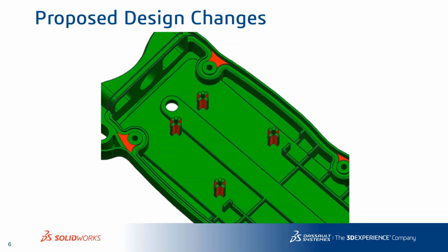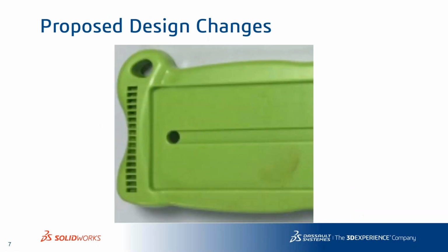And then on the other side, there were a lot of sink marks that I had to make some changes to. That area in that photo right there was just awful looking. So I really had some eyeballs looking at me like, what are we going to do? So my fix for those sink marks was to put those little square indents in there to take the plastic out where it was too thick and give it a uniform wall thickness, which made it look racy, if you will.